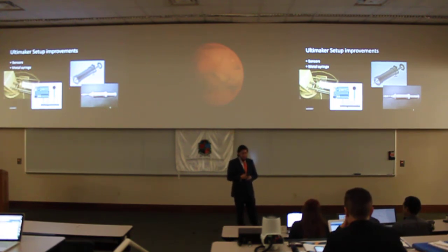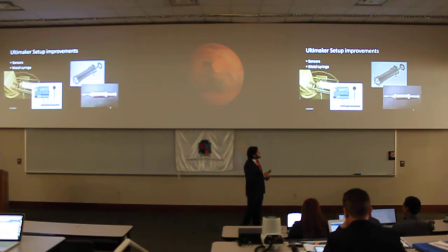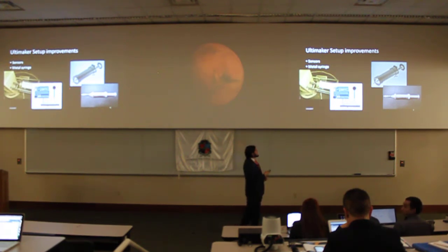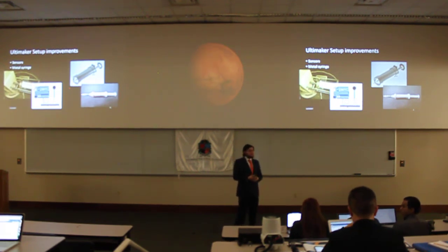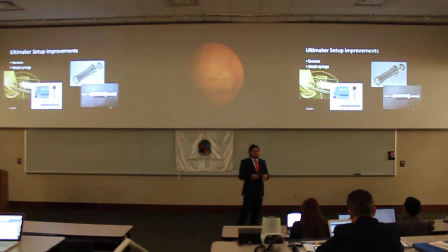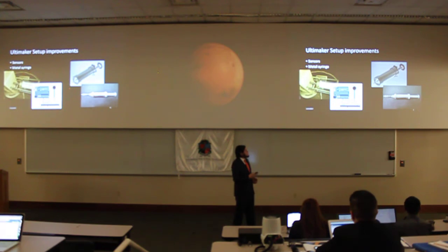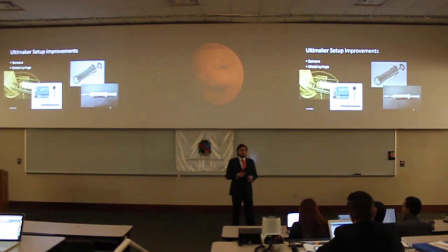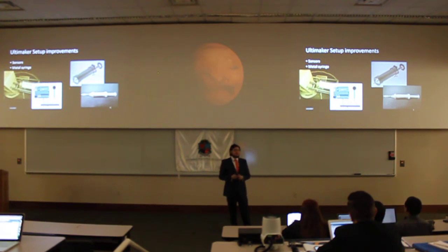So the improvements were mainly three. First, we implemented a system of sensors which allow us to characterize better the process of printing. These sensors relate position in the printing and the pressure that is being exerted on the printer to improve the characterization of how the fluid is changing and how the flow is changing. The next part was to develop a metal syringe system, since currently there is one made of plastic.